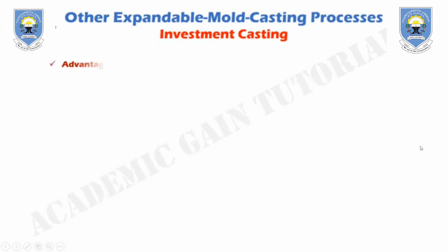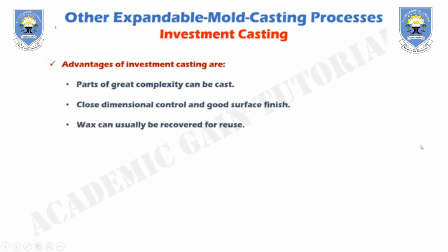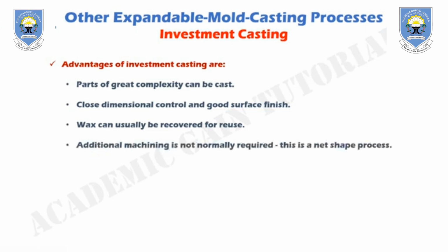Advantages of investment casting are: parts of great complexity can be cast, close dimensional control and good surface finish. Wax can usually be recovered for reuse. Additional machining is not normally required. This is a net shape process.